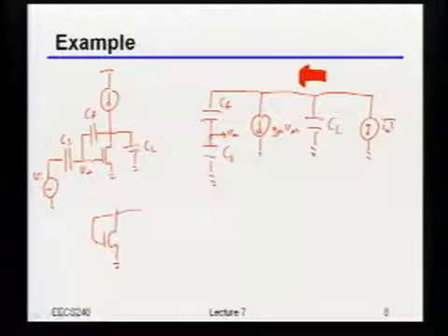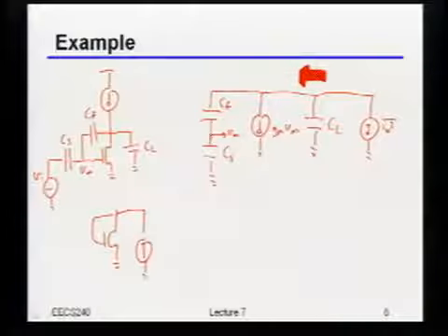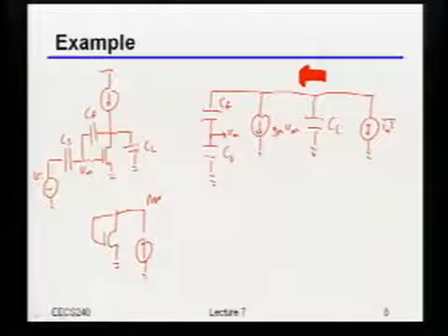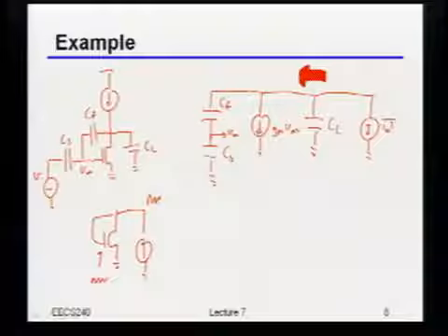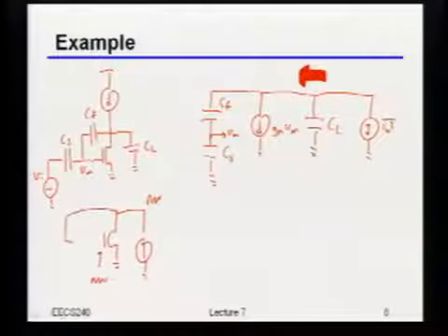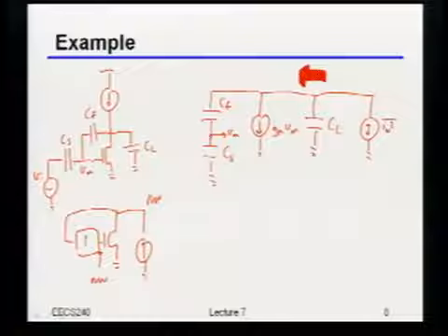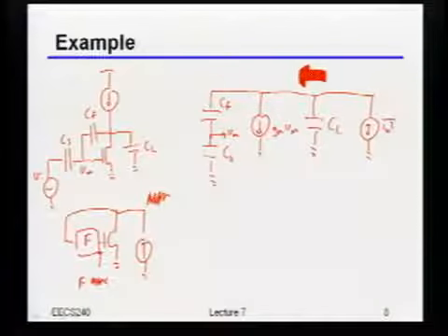Well, certainly if I dumped some current into that right there, I'd definitely get 1 over GM, right? So why do I claim it's not exactly 1 over GM here? What's a little bit different about this particular circuit? You have a capacitive divider. Yeah, I've basically got a divider there, right? So if I look at the voltage wiggle right here, I don't exactly get the same voltage wiggle right there. What I actually get, and I'll go back to my ideal mathematical thing, is some feedback gain ratio there, right? So if I had some wiggle right there, I'm going to get the same wiggle, but just multiplied by f, right?